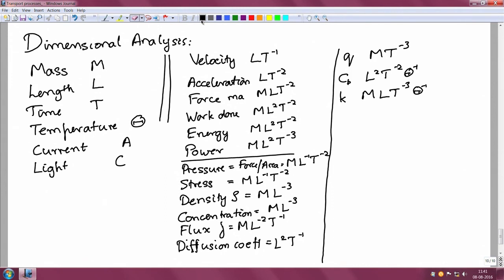The stress, of course, I have already derived for you. The stress has the same dimension as the pressure. How do I get the viscosity? I need some relationship in which I know the dimensions of all quantities apart from the viscosity. And that one is, of course, Newton's law for viscosity, which basically states that the shear stress tau is equal to mu delta U by L.